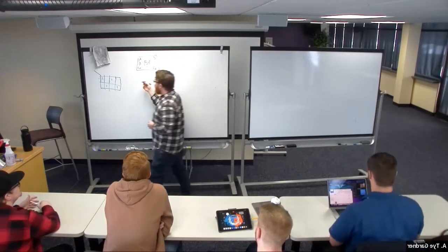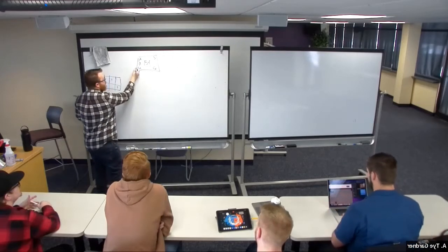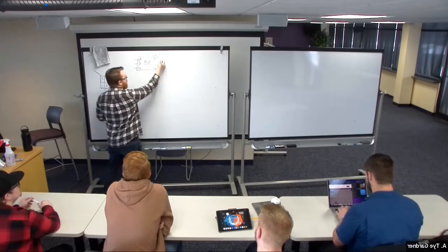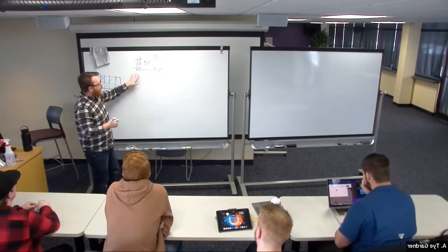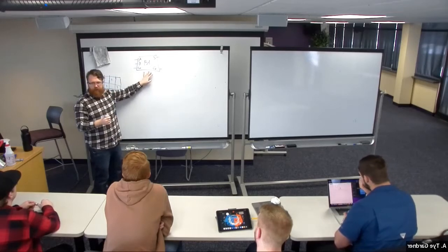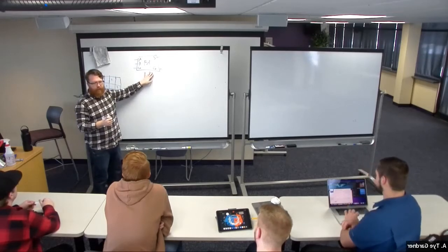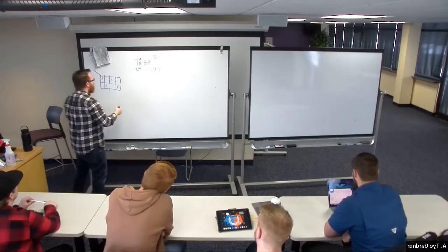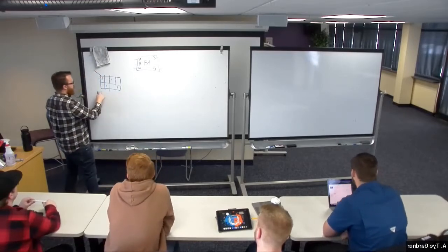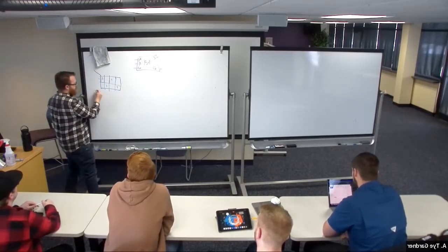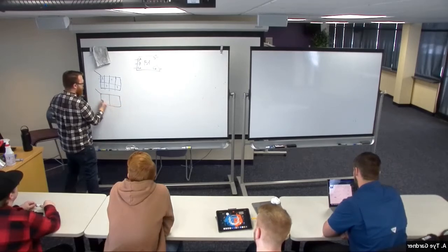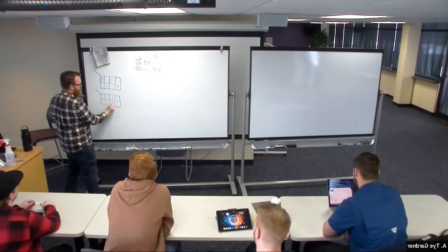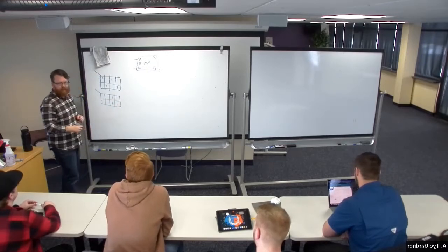And so when we do this, we're going to design just a full adder, which is going to have a carry in, right? And hopefully most of you have your full adder built and tested by this point, because it's as simple as saying, well, the carry out, its K-map ends up like that or something.